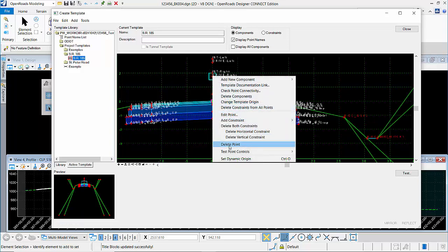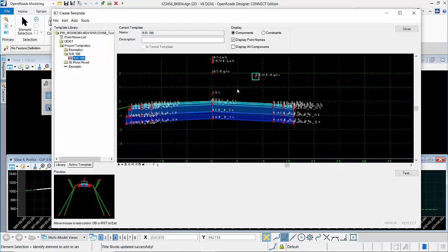If I find a drive to the right, the steps and the end conditions disappear. Of course, depending on the drive buildup, you may end up not keeping the steps too. If you're coming up against a commercial drive with quite a substantial buildup, maybe that's going to be kept instead of the steps. So you can configure this as necessary to remove whichever you need.